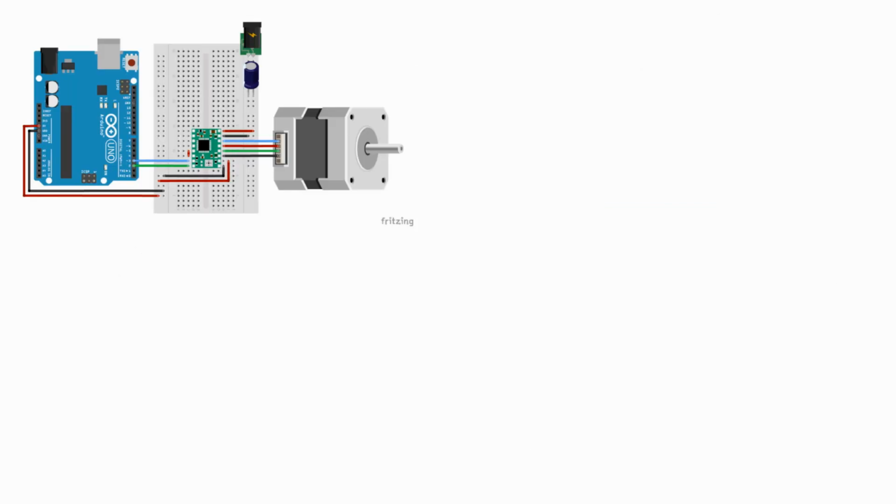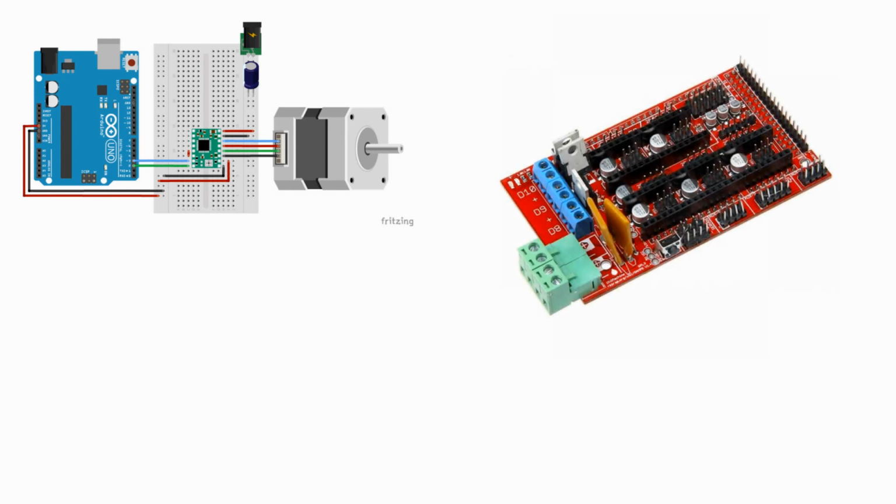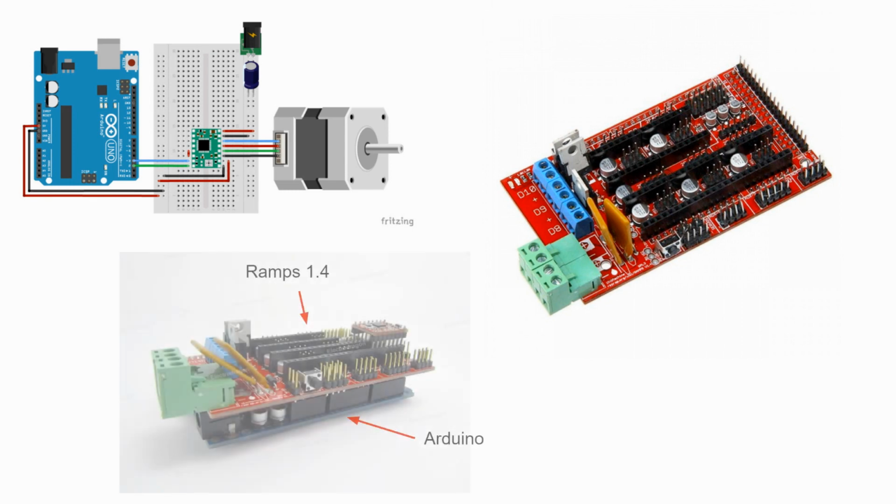The connections look like this. We need 6 stepper motors for the Rubik's Cube solver. As we can imagine, if we connect all 6 motors to Arduino in this way, the wiring will be very messy. Instead, I use the RAMPS 1.4 control panel. It's an Arduino Mega Shield. You can plug it right on top of Arduino, just like Raspberry Pi's head.